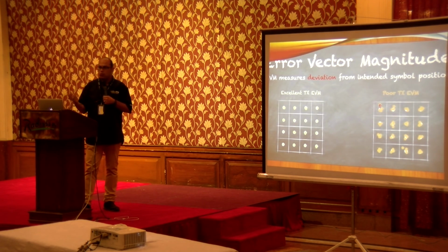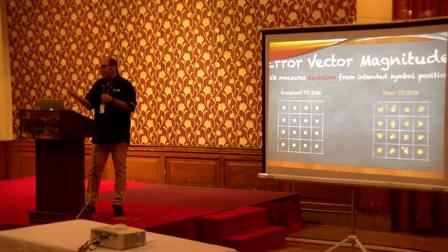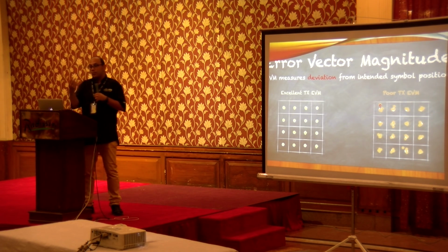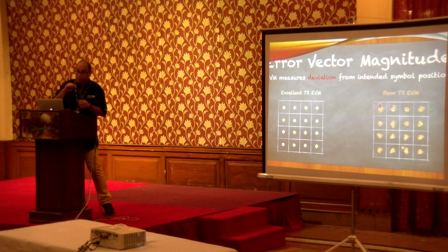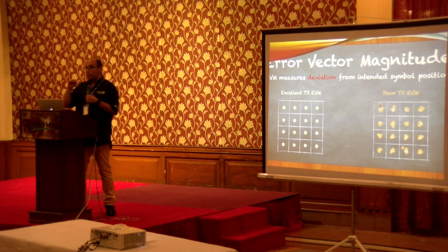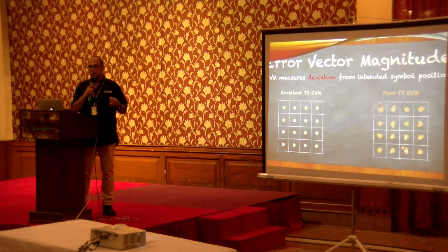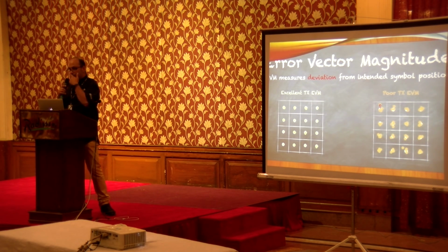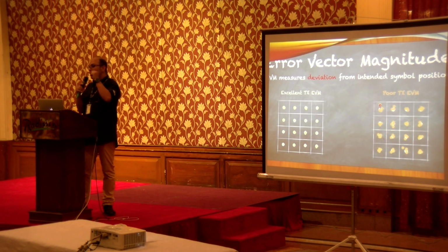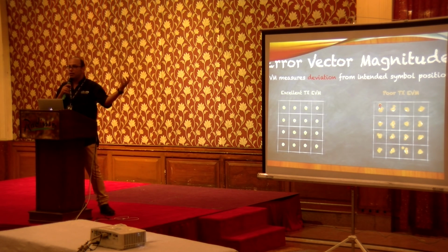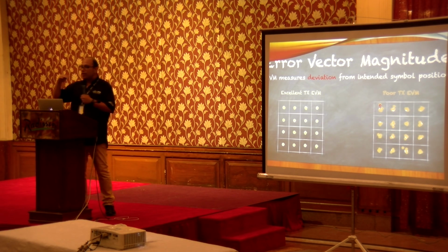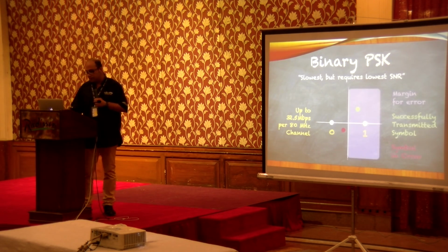We call it retransmission. What is retransmission? Because of the effect of noise or interference, the packet, or better to say the frame, is lost on the way. This is packet loss or frame loss, because this is a layer 2 technology. Better to say frame loss. When you have a frame loss, you need to retransmit again. This is retransmission. And the amount of EVM shows the amount of retransmission, or how clean you can receive your symbols. So EVM shows the level of quality, actually.